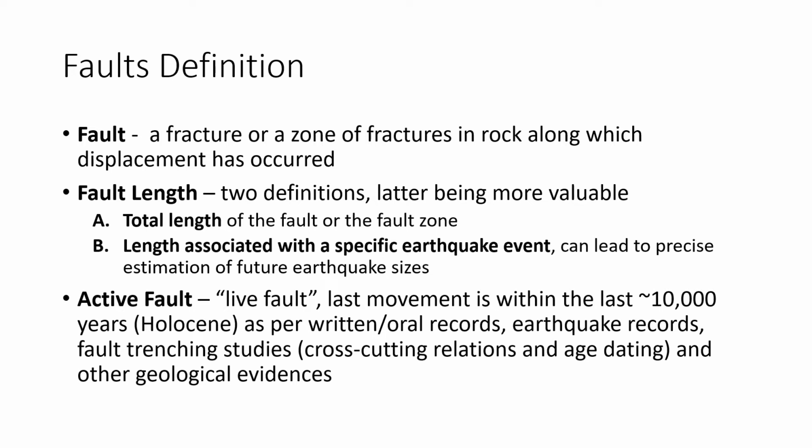Another basis of your age of earthquake is your fault trenching. This literally involves going to the trace of the fault. So you go out to the field, you look for the fault, and then you dig perpendicular to the trace of the fault, and from there you can see the cross-cutting relations and the stratigraphy. Okay, so basically, if your fault is cutting through your Holocene sediments, it means it is younger than your Holocene sediments, and therefore its last movement is within 10,000 years, and therefore it might be an active fault.